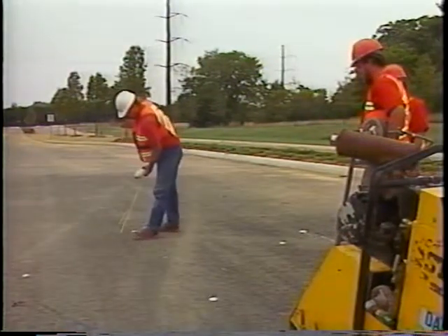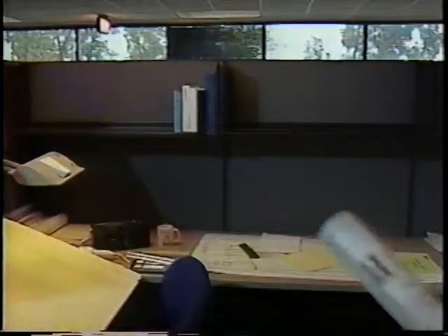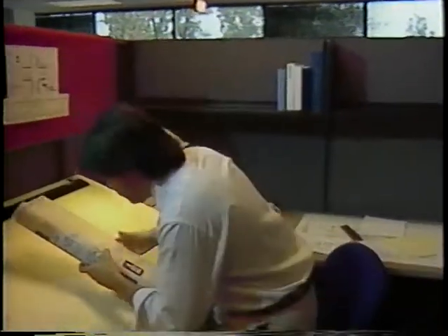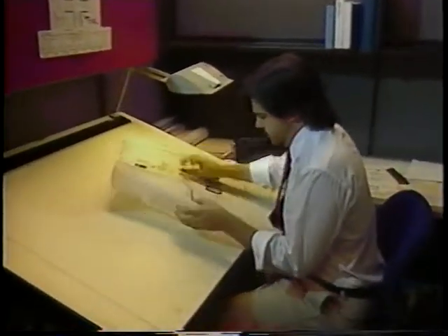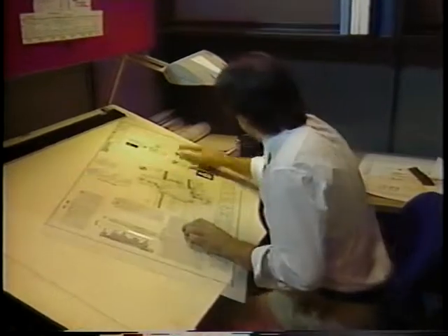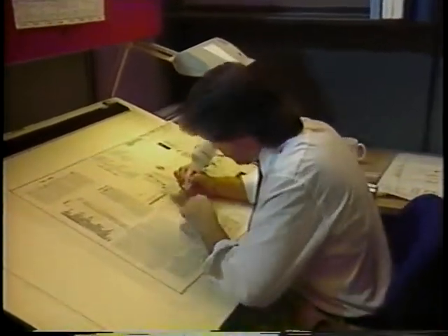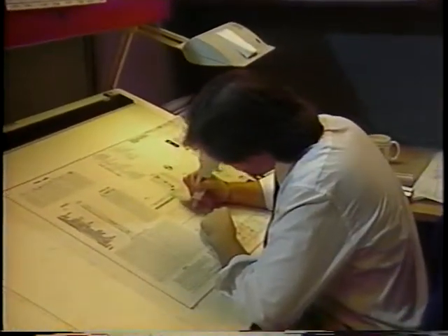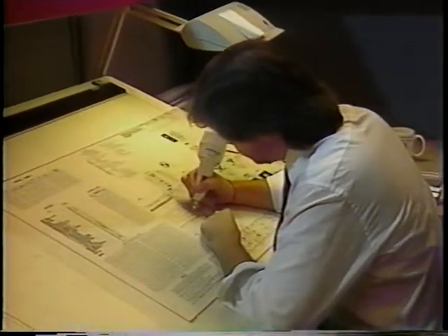If the detector installation is to be performed by a contractor, the scale drawing becomes part of the procurement package. The completed drawing should be reviewed with the design engineer. This ensures that the loops or probes are located as specified in areas free of any underground hardware that could interfere with detector operation.